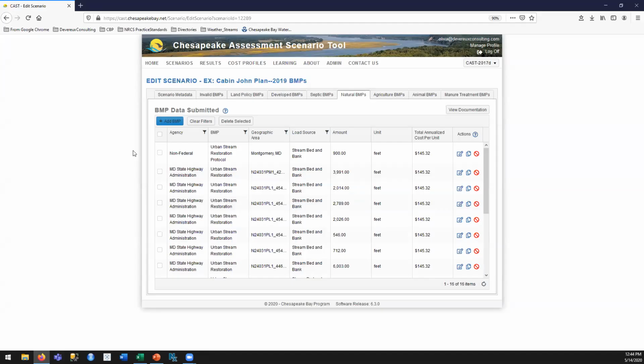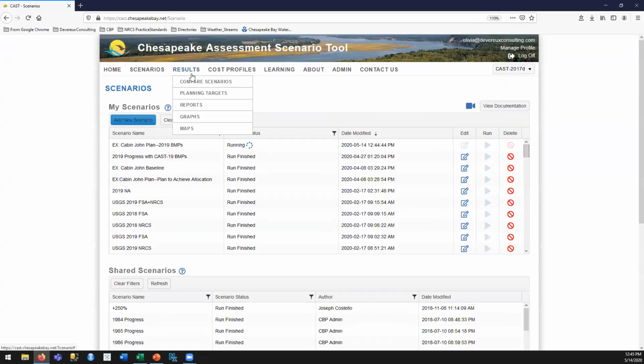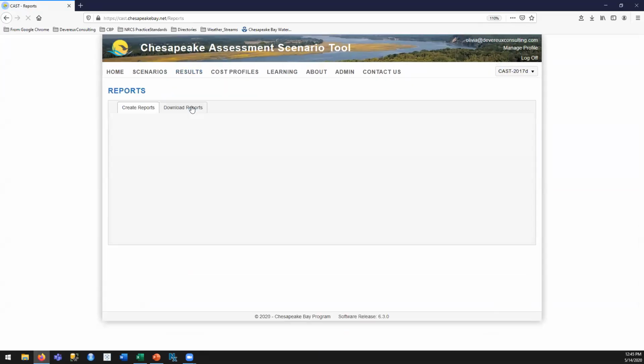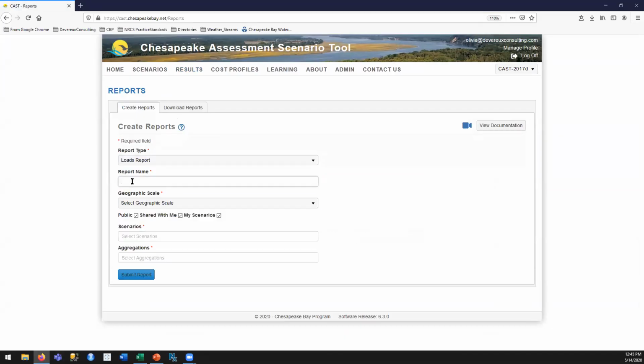So that's already added. And what I'm going to do is go back to my scenario list, and I've edited that scenario, and I'm going to run it. And then when I want to go see the results, I'm going to go under results. Let me make this a little bigger on the screen. I'm going to go under results, reports, and I can select my report type. And I'm going to want to look at a loads report. And I give my report a name,